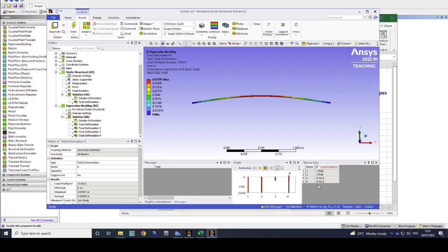So there's a 40 newton difference, and this is related to some of the errors that we have when we convert our mathematical model into a finite element model. So now you know that this error is related to discretization. If I increase the number of elements that I'm using here, I can manage and reduce that error. But to be honest, 40 out of 3,100 is really small, so we can accept that difference.